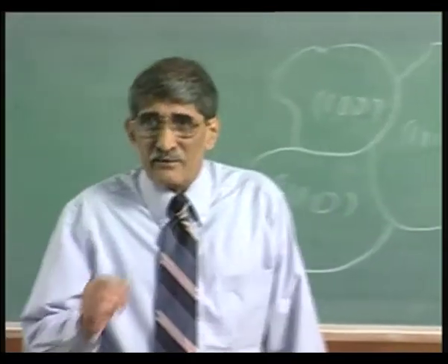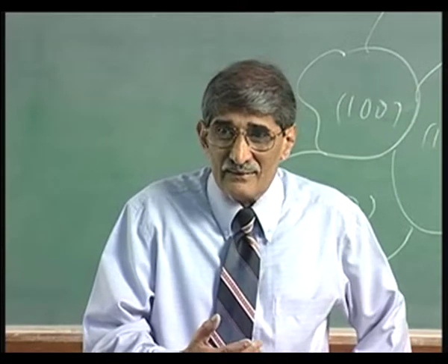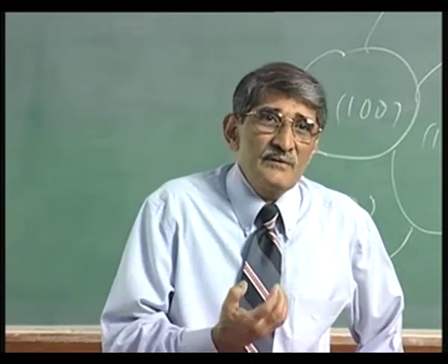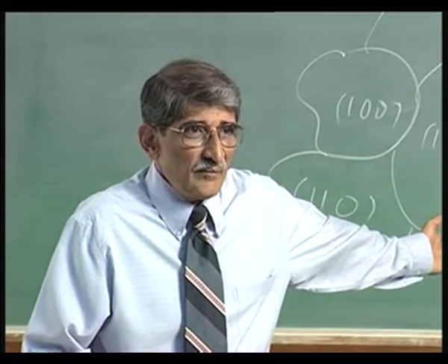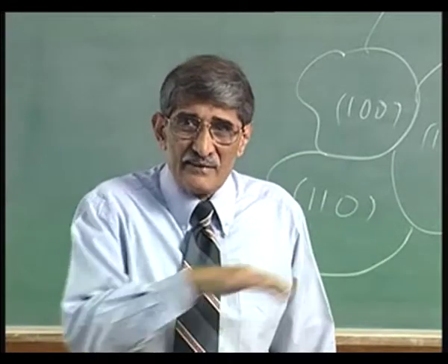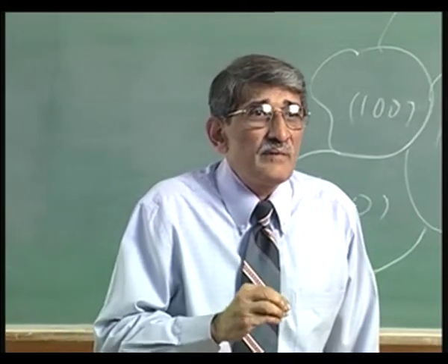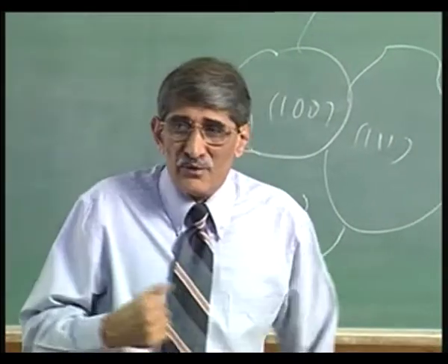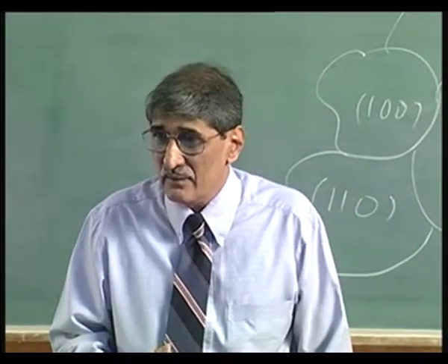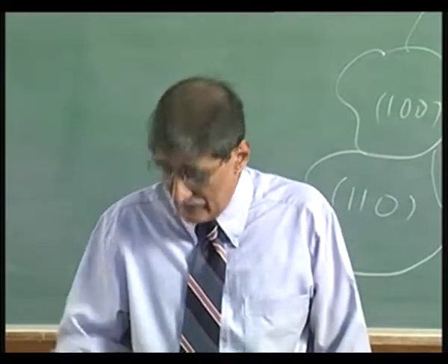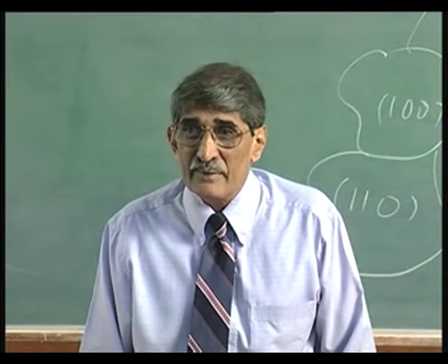Okay. Now, let us not spend our time too much on silicon epitaxy. This is relevant if you are thinking of silicon on sapphire, that is the same process. Silane broken up into silicon and hydrogen. Take a sapphire substrate, jack the temperature to 1000, do the deposition. In fact, that is one of the materials used for making high speed MOS devices. So, that is why it is relevant to this discussion. But if you are talking of compound semiconductors only, then let us see what are the things. So, that is the basic process that is involved in epitaxy.